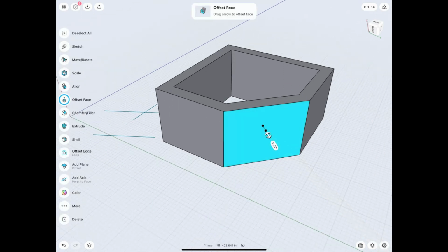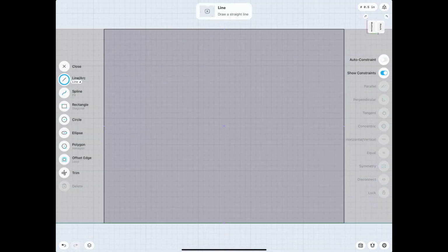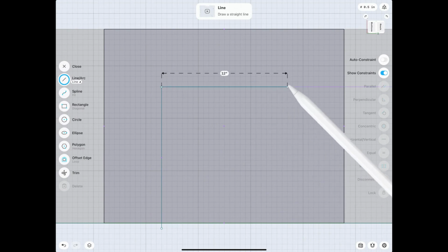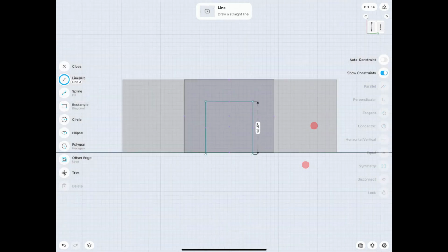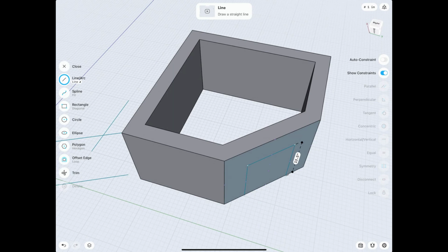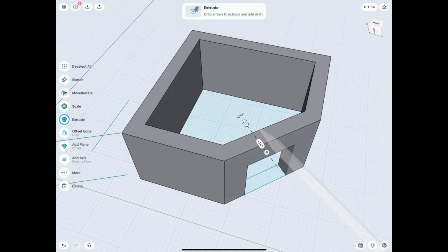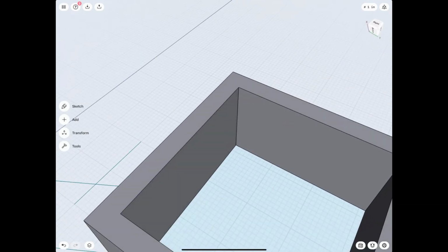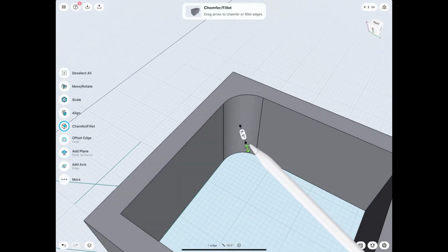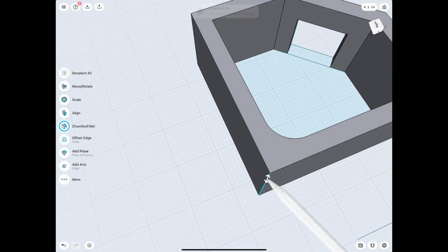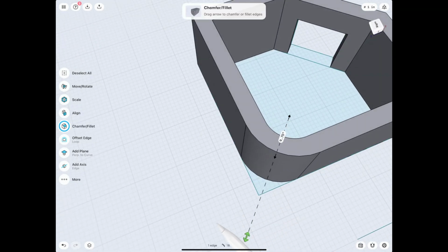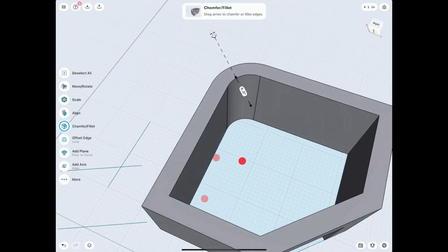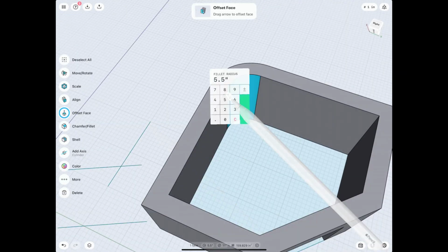Select a face with a finger, double tap onto it. We started drawing on this face now. Draw something up, draw something there, draw something down. Two fingers pinch out, one finger rotate, select the fill, move this in, there's a cut. Super. So here's something SketchUp is bad at. Look at how clean these arcs are. Nice. And we can even select this and let's say, oh, it should be 5 inches.